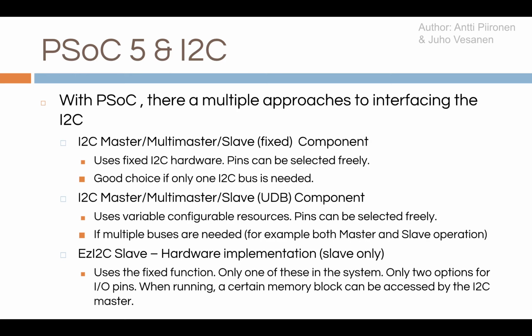Practically it's a part of EEPROM, so after programming the I2C slave stays alive, and you can then read or write data from an I2C master processor, and have the data, for example from the data acquisition system you already have here, available for other processors using the I2C bus. That's just an idea.